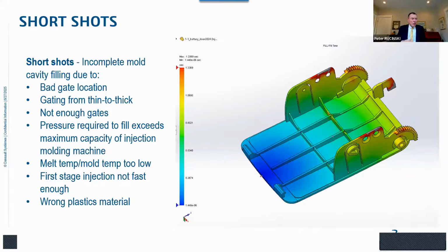So it could be that we have to move from a higher molecular weight formulation of polypropylene to a slightly lower molecular weight that will have lower viscosity, lower resistance to flow. Now we can properly fill and pack our mold. So it's kind of amazing, just one defect here, multiple causes, often very difficult to know what the exact cause is unless you're using simulation.